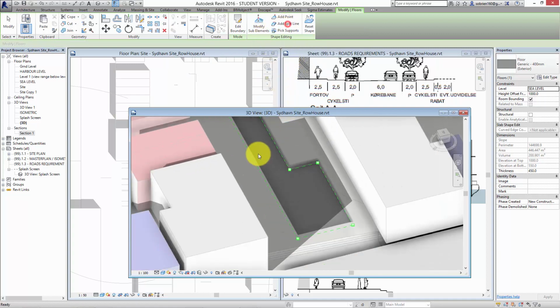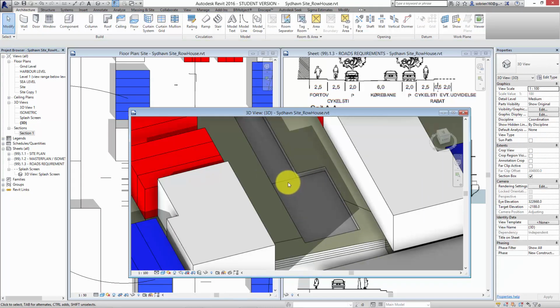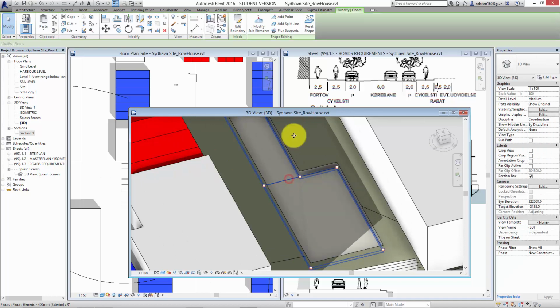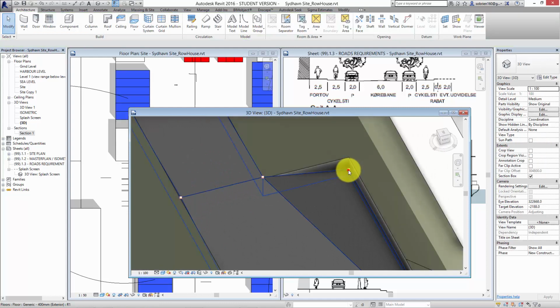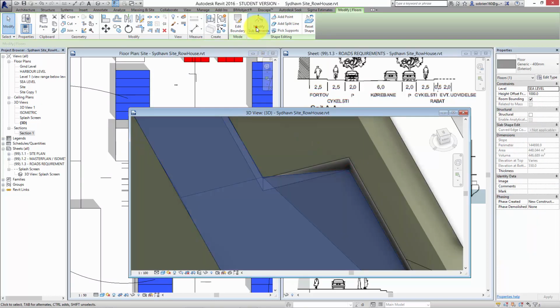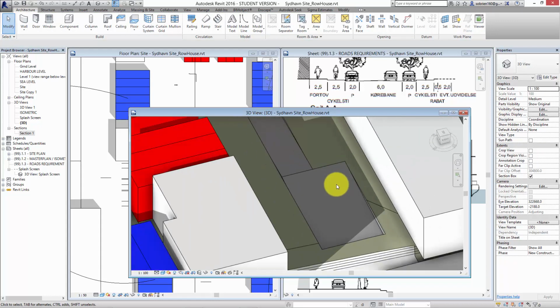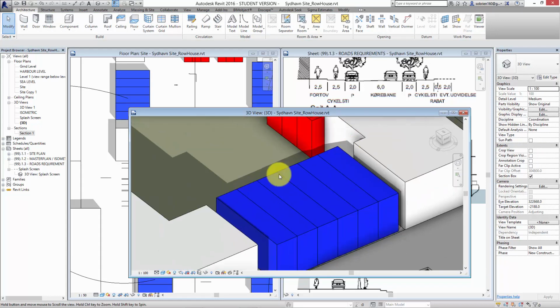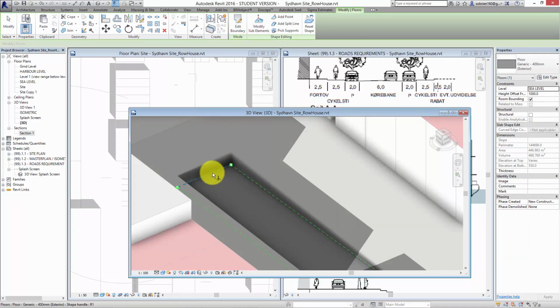I can do certain things, as in I can add a split line here from here across, and I can then select, by modifying the sub-elements, lines, which I can type in 1200 for example, specific levels, or I can select individual points, which I can select there, modify sub-elements, select the point. It's a little bit hard to catch sometimes, but you can basically control the slopes of the road just by modifying these different sub-elements in here.